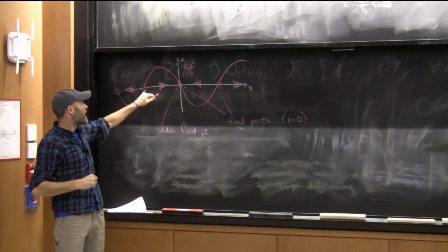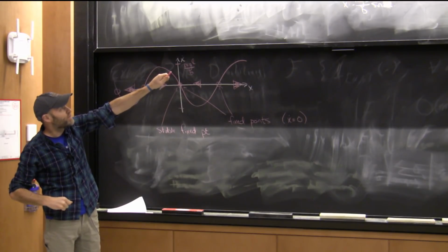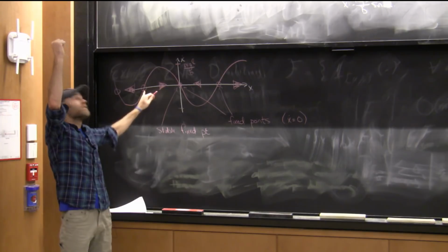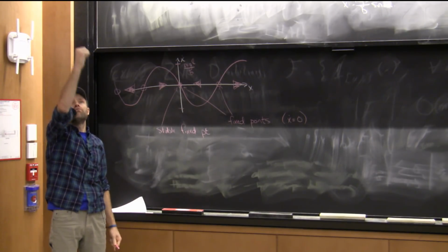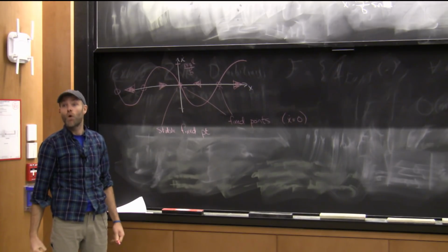Why is it so simple? What is this over-damped regime, this regime of making it first order? That's saying that my damping is so big that when I go a little bit here, it just goes really slowly down, and it doesn't even overshoot. That's the over-damped regime.